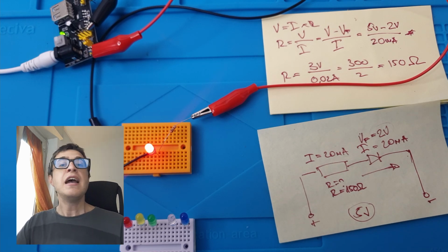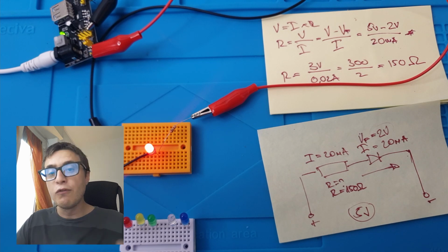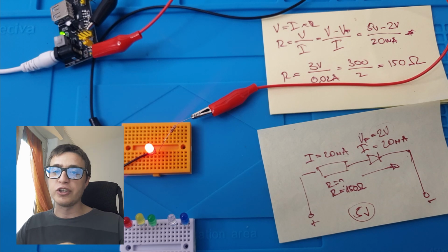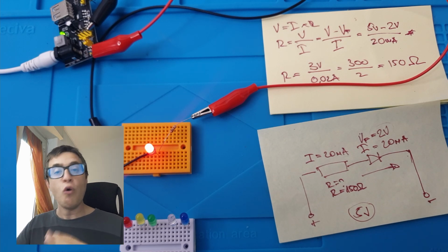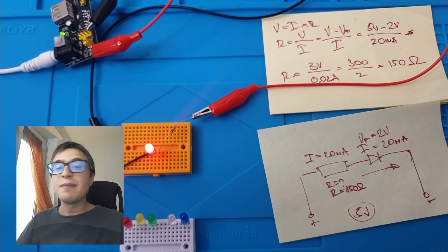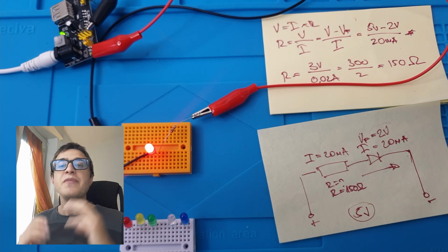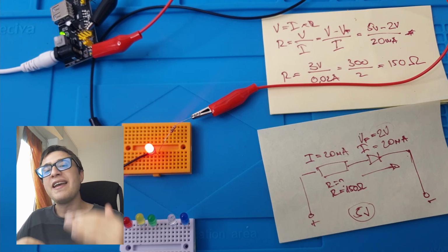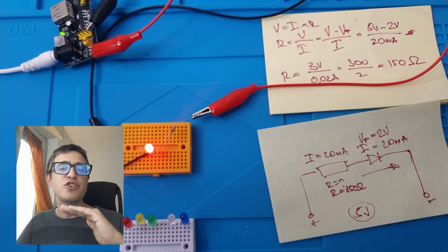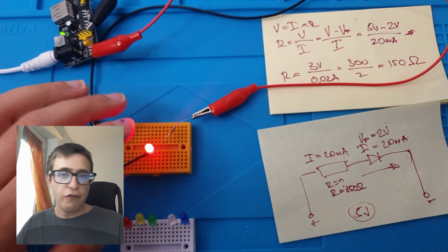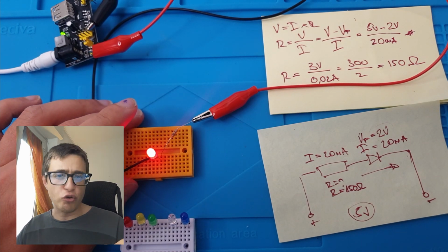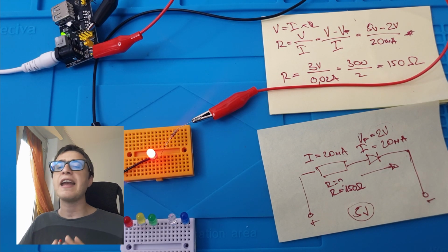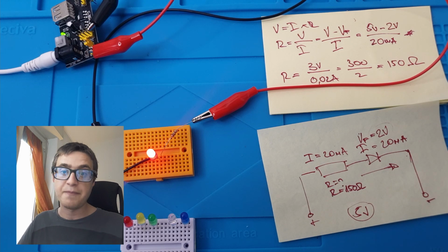But the most important thing is to see the maximum voltage from the datasheet and not to go over that voltage. Because if you go over that voltage, your LED light at the moment will not show any difference, but it will decrease the lifetime of the LED light. So it's important to be below that threshold of maximum voltage, which for the red LED light is 2.2 volts. So that's it. You can use this calculation for any circuit everywhere you need to insert an LED light.